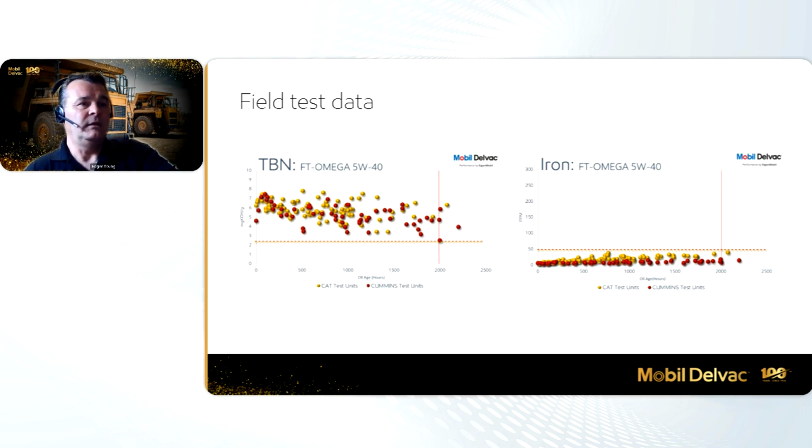And it seems like it is still slightly climbing linear. However, it's almost a flat line as well, from 0 to 2,000, 2,200 hours. So very impressive. I think some C175 Cat engines say their upper limit is actually 70 ppm at 500 hours. So we didn't even get close to that. Very good results.